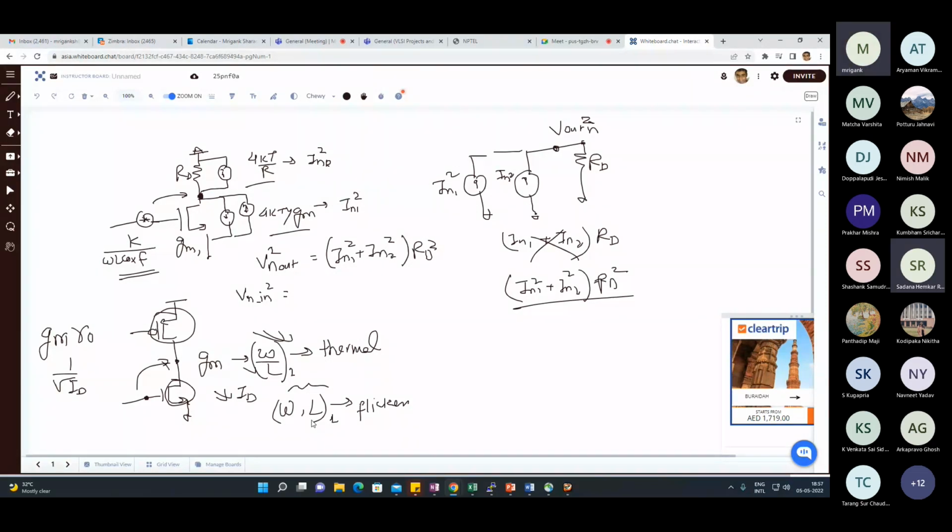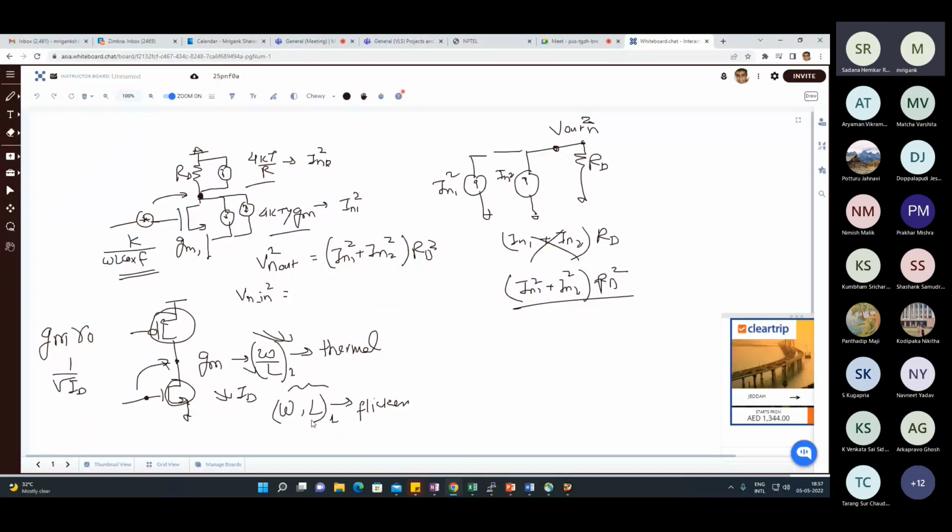Sir, while analyzing the frequency response using the Miller method, you said that we won't be getting the zeros. So while plotting the Bode plot without using zeros, won't that analysis be inappropriate? Yeah, so this becomes more important when you have stability in closed loop circuits. There, zeros become important, and we need to take care of the zeros and their positions in the overall phase response. In open loop circuits, it still has effects, of course, because it will change the slope at certain points. But the speed limitation mostly comes from poles.